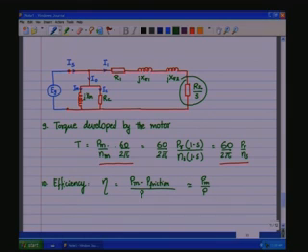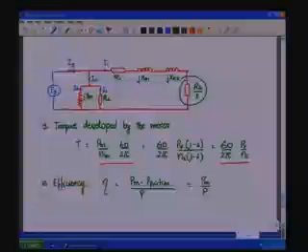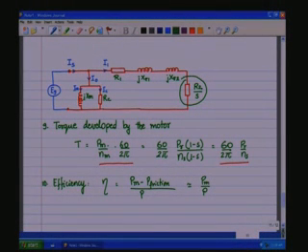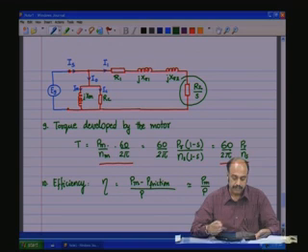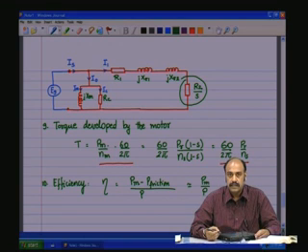So by reversal of polarity, it could be the reversal in the voltage polarity or reversal in the current, because it is now acting against I1, and then it will pump more current than I1, and therefore the current reverses, and therefore the power flow is from the mechanical side to the electrical side. So the same equivalent circuit can be used even for the induction generator. We will work out a very simple example of the induction generator in the next class, and then conclude the topic of the induction motor.